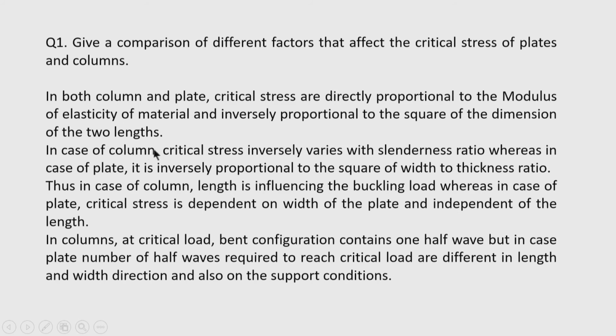Now, in case of column, critical stress is inversely proportional to the slenderness ratio, whereas in case of plate it is inversely proportional to the square of the width to thickness ratio, that we have observed from the derivation. Thus, in case of column, length is influencing the buckling load, whereas in case of plate, critical stress is dependent on width of the plate and independent of the length.